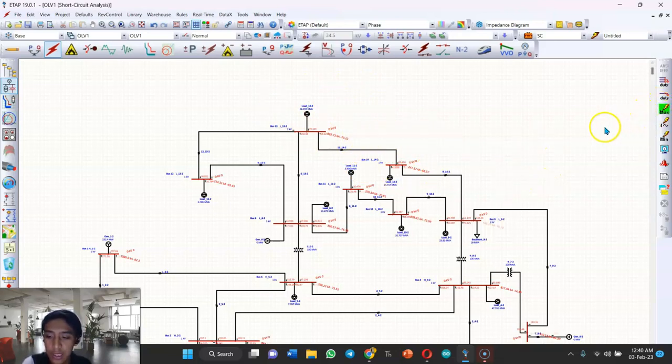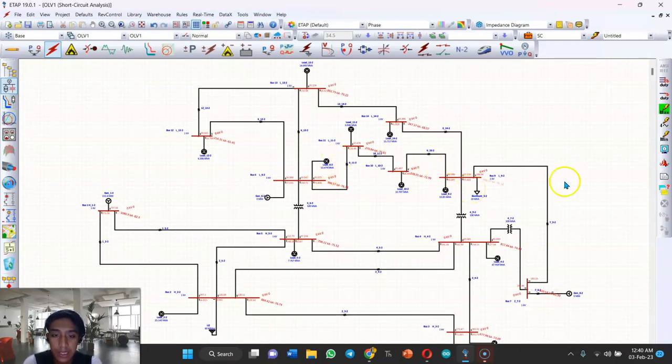For the conclusion on load flow and short circuit analysis: they are critical in the design of electrical power systems, and these two types of analysis are used in this project to study system behavior and give recommendations for improvement. For example, short circuit analysis is essential to verify that equipment is protected by protective devices with adequate interrupting ratings, such as circuit breakers and fuses. If the current exceeds the interrupting rating, the effect is destructive.